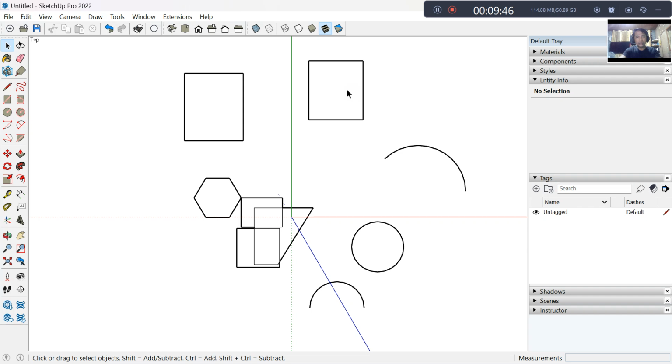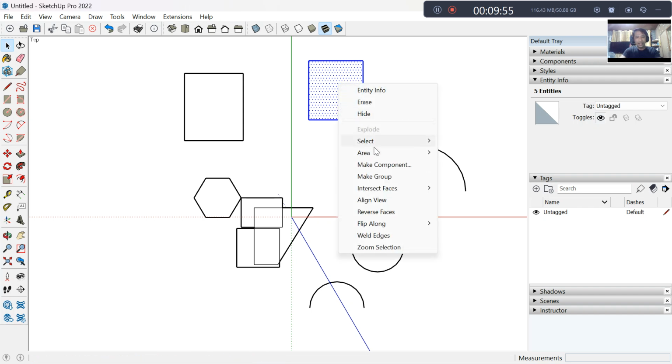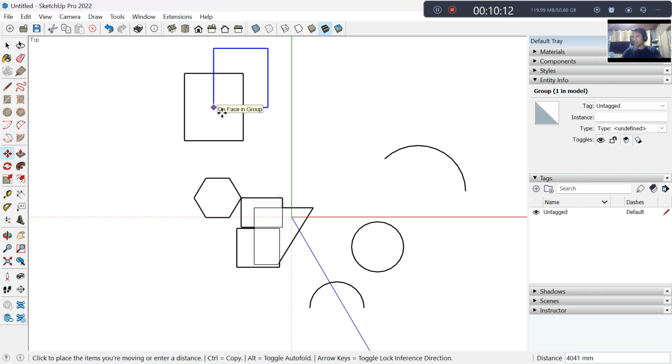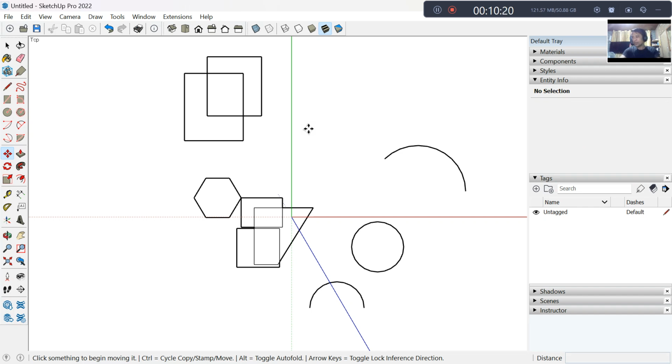And then also with this, triple click, 1, 2, 3, then putting the selection tool inside, right click, then make a group. Now, I will just move the group object, putting it here, and try to move the endpoint. See, these objects will not stick to one another. So, in SketchUp, when you group an object and place it into another object like this, they will not stick to one another. So, in SketchUp, you have to group early and you have to group often.